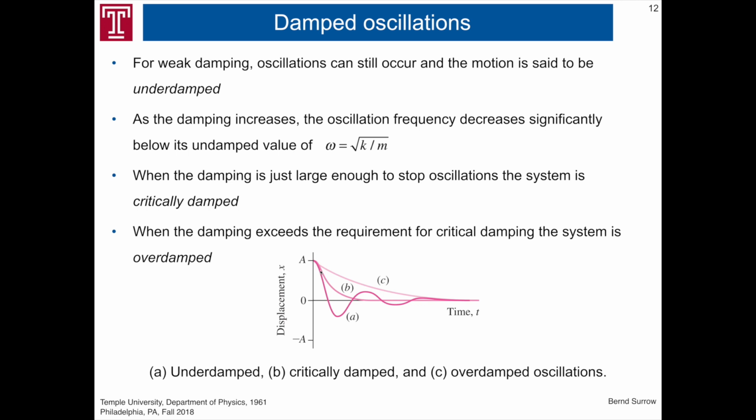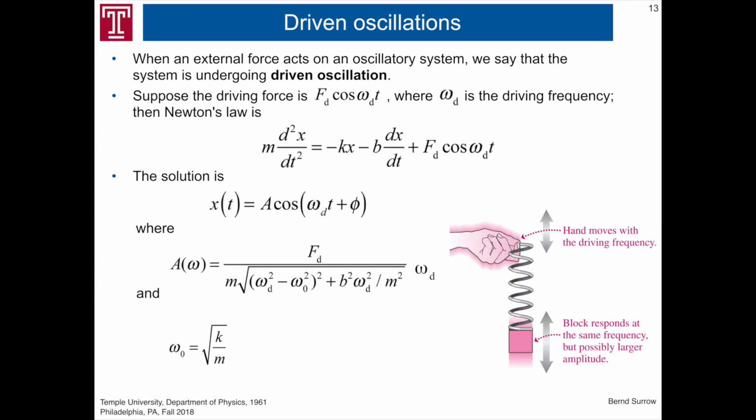Now, if in addition to that I have a spring mass system, I have velocity dependent friction, and I'm now perturbing that system in a periodic way, but in a way which is completely independent of that oscillating system of a spring and mass. This is quite complex to solve. You will get a solution of the form x of t equals the amplitude times cosine omega t plus phi, but the amplitude depends on the frequency.